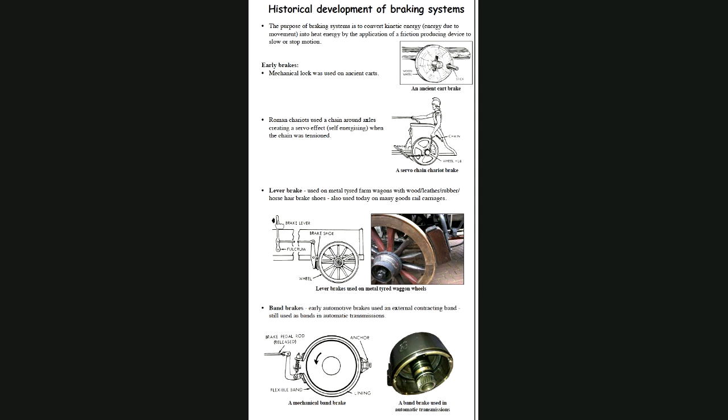So the fellow pushes that forward, and there's a big lever arm there compared to there, so that's going to create a big force along here. It has to move a lot further, but it creates a high force on there. But all that's doing is just by friction, just stopping the wheel from turning without any servoing effect, not like this here.